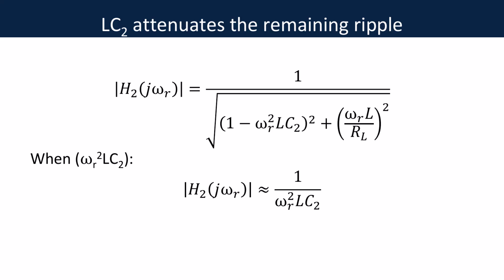This step treats the pi filter as two cascaded smoothing actions. It is convenient for initial design, but the stages are not perfectly independent because the rectifier charging process and source impedance influence the waveform at C1.